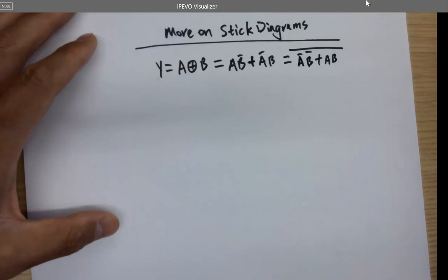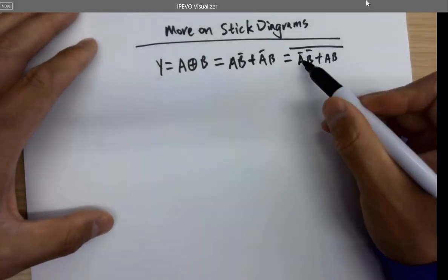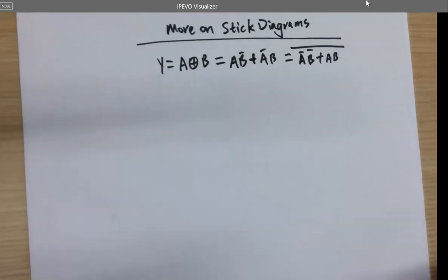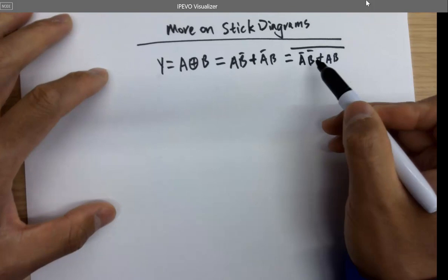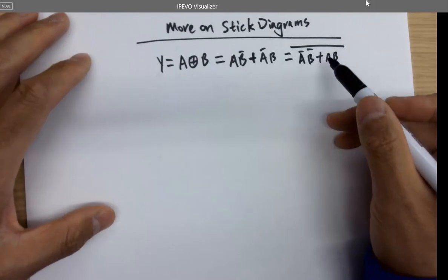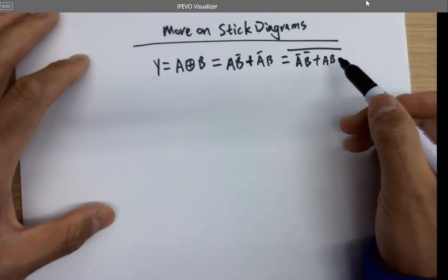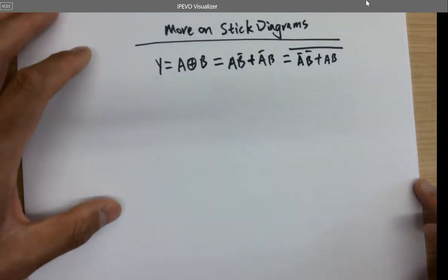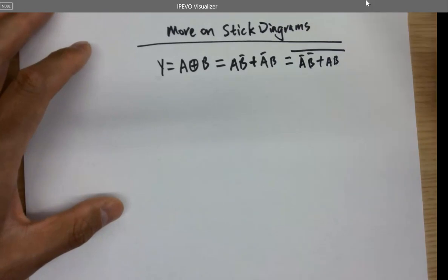Okay. We are basically designing a transistor circuit first. So I have to find out the AOI logic and draw the schematic in transistors, and then convert into stick diagrams. There are two components in the process. So the first step is to draw the transistor level schematic. Okay. So before I move forward, I'm going to ask you one more question. Why do we want to do that always? For manually laying out the circuit.